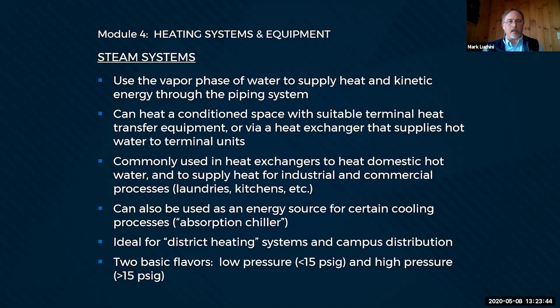Now, if you worked on college campuses or hospital campuses, places like that, some of you are probably saying, well, hey, what about medium pressure steam? Steam systems are classified as low pressure or high pressure, but the way people use them, they have different descriptions. For example, at Harvard, they'll run their low pressure systems at about 10 pounds. Then they'll have medium pressure at about 45 to 50 pounds, and their high pressure system runs around 120.